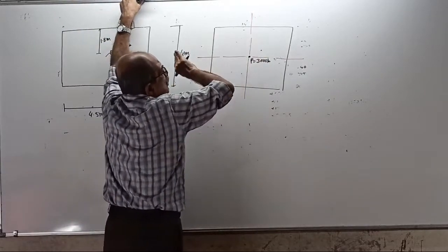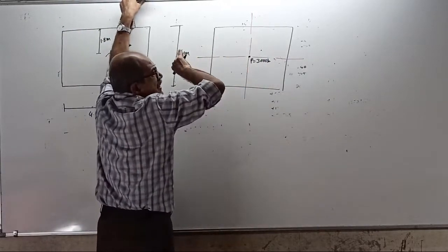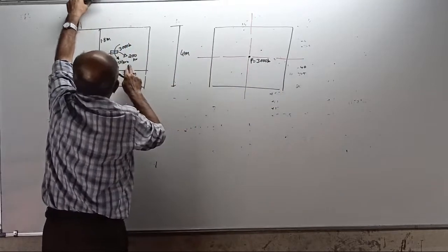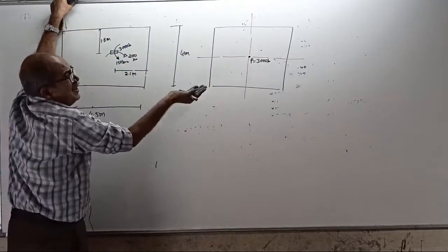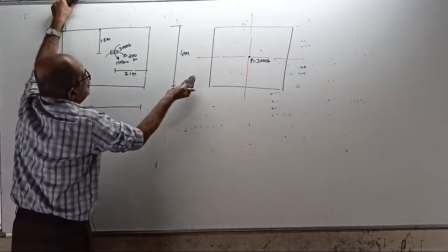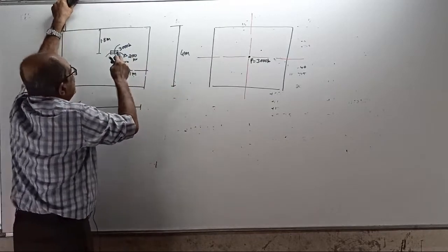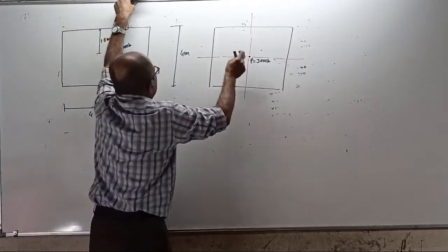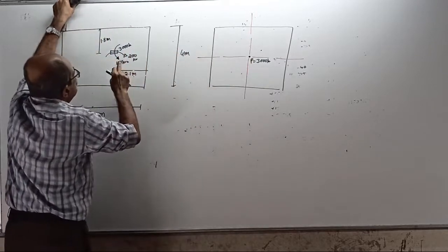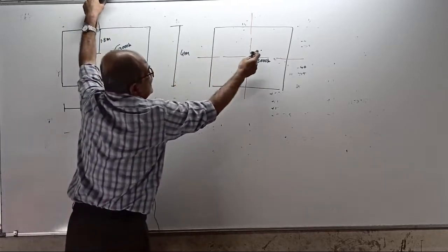Now, see, this 3000 kN load is acting somewhere here. It will create a moment like this, a moment like this. But the column has one more moment that way. See, there is a column moment of 200 here. So, when you shift this eccentric column here, it will create a moment of that load into this eccentricity.